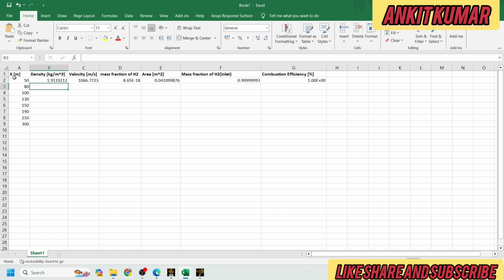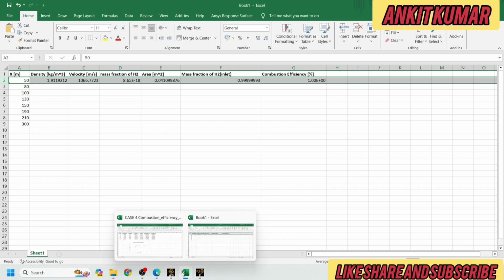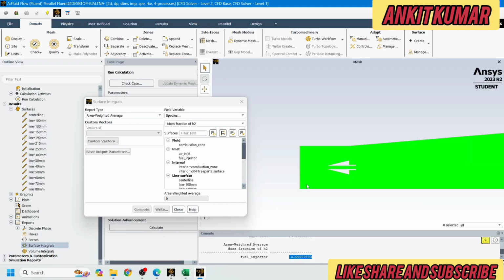So we will not use this 50 mm value. We will select those lines which are just after the injector, because we are calculating combustion efficiency. For that we need hydrogen and oxygen to get combustion. Since no hydrogen is there at 50 mm, no combustion is happening, so the combustion efficiency is coming as 1. So we will choose the line at 80 mm and calculate the values.